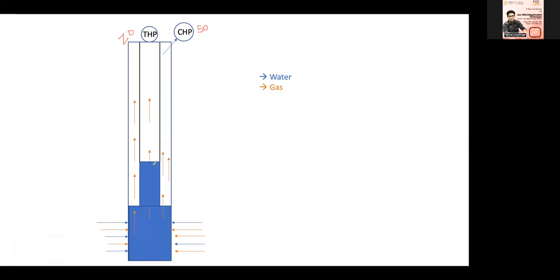Because of the hydrostatic pressure of the water that will act against your reservoir, some of your gas will move towards the casing annulus, and you will eventually see your tubing filled with liquid. So in this case, your tubing pressure may decrease to 0 or your casing pressure may increase to 70 kg, because instead of going to the tubing, the gas will go to the casing side. From this difference in tubing and casing pressure, you will be able to know about liquid loading.